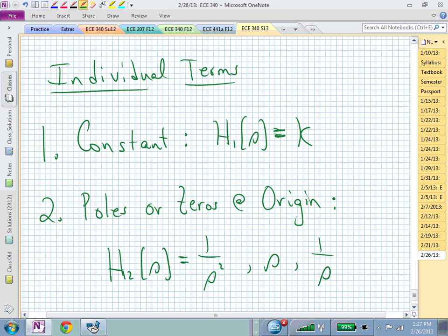If you put a signal into a system and integrate it, and out pops its result after integration, the system behavior in the frequency domain would just be this 1 over s. And we want to figure out how to plot that as far as its Bode plot. If this is an integration in the time domain, what is a zero at the origin? A differentiation. And we'll learn that it looks something like this in terms of its magnitude behavior in the frequency domain.